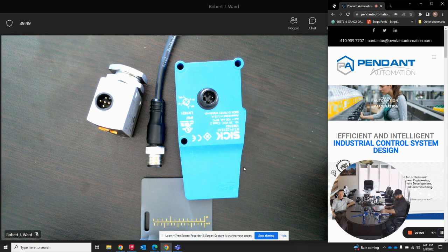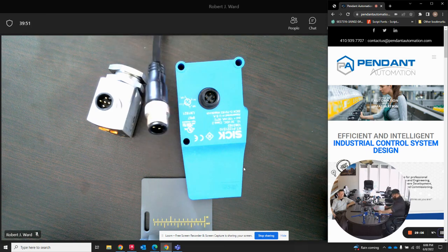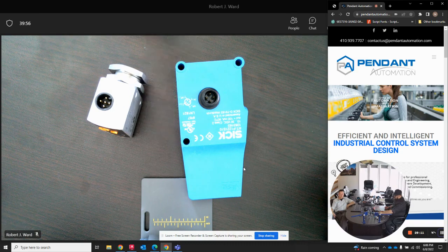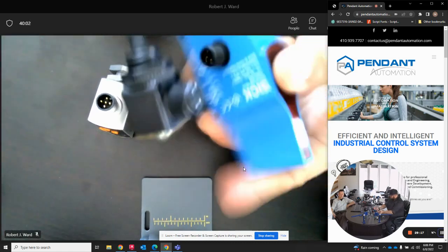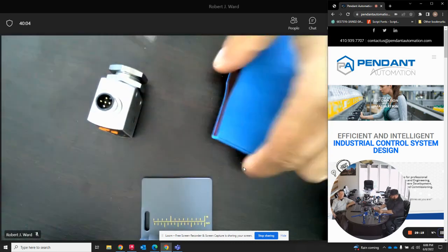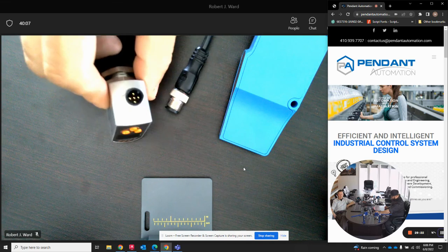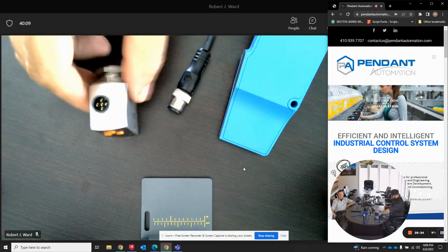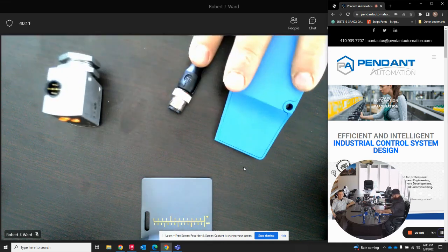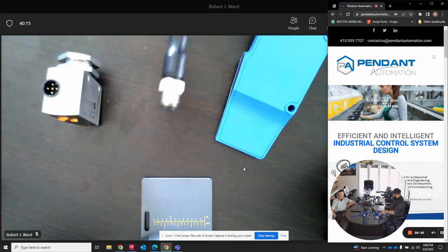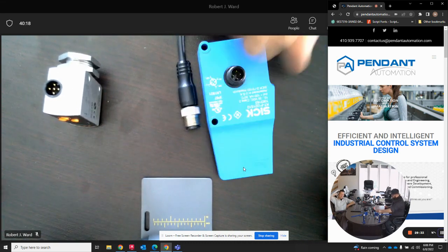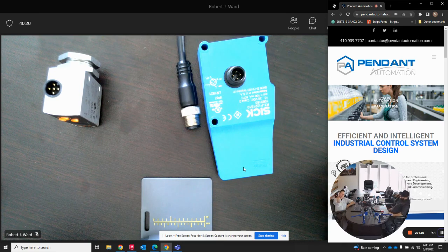And since this is what we call M12 or Eurofast, it's also mostly universal. So if it's a DC, say 4-pin M12, it's going to work. For example, that same 4-pin would work for both of these separate sensors. Right. When you get complicated sensors, there are 5 pins, and there are many more, but the common is going to be a 5-pin and a 4-pin. But for our standard, I bet you 99% of ours is going to be the 4-pin M12, which is shown on these two sensors. And so that is something to take into consideration.